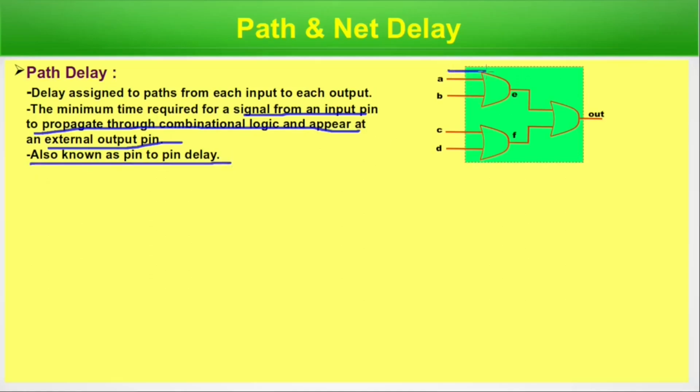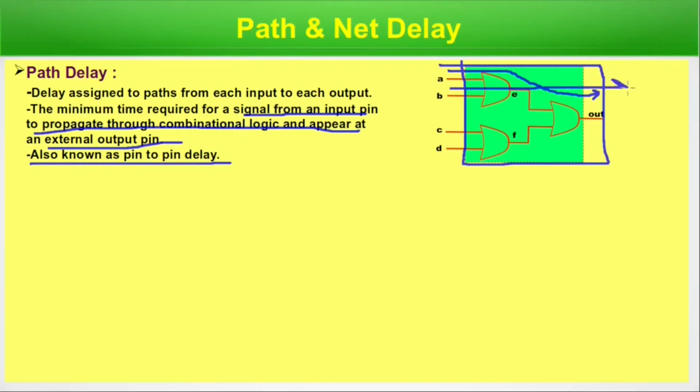The time taken by a signal traveling through this path is the delay. It's combinational logic and no clock is involved here. So how long it takes for the signal to travel from this input to the output is measured as pin-to-pin delay or path delay.